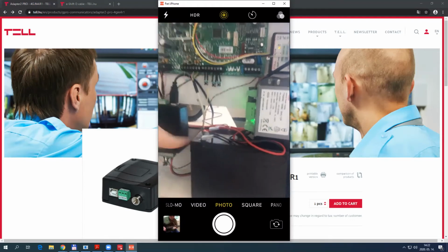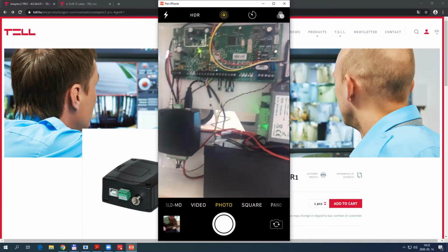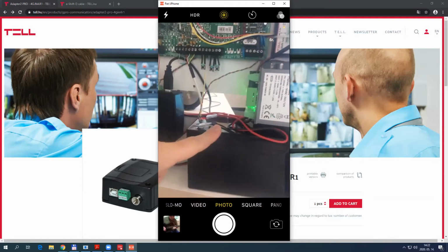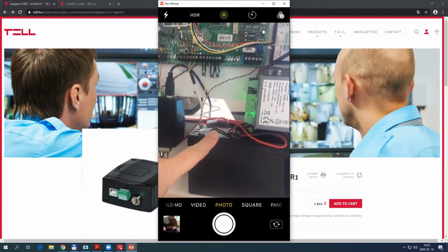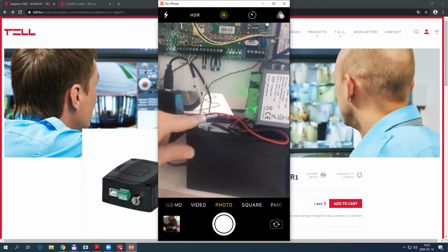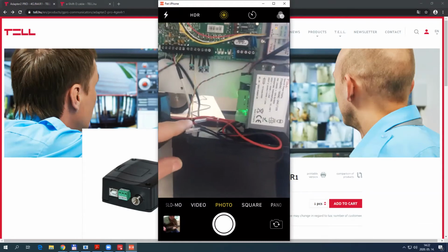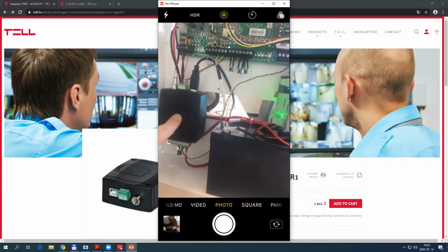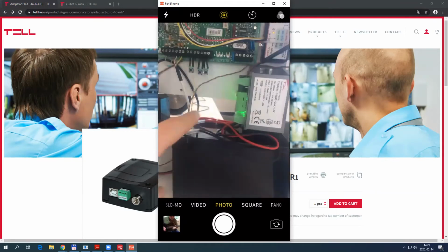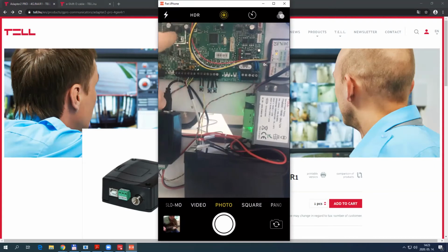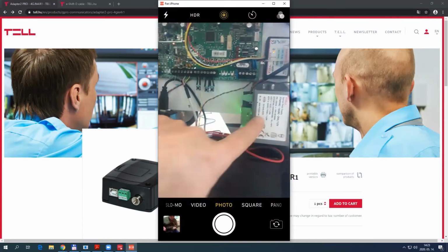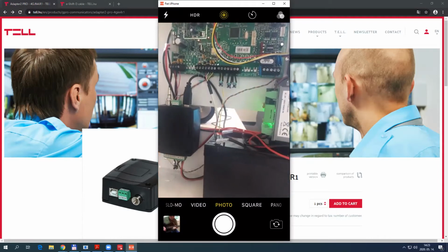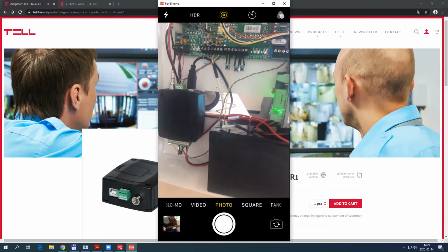So when there is a normal operation, the alarm control panel can charge the battery and can use the battery. And when there is a mains loss, in that case, the power supply will switch the battery automatically to the adapter as well. So the battery will still be connected to the alarm system and will supply the alarm system, but through the power supply, it will also be connected to the adapter 2.